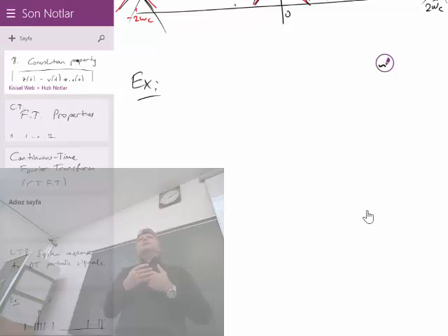Usually the filters are designed in the low-pass domain. And high-pass filters or band-pass filters are not very good. They have lousy transitions. So if you want to have a very good band-pass filter, what you do is you shift your band-pass signal towards the origin first in the frequency domain.